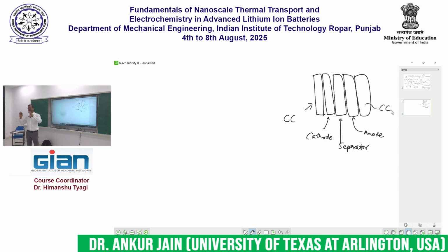So if you think of a cylindrical lithium ion cell that has a jelly roll of this sandwich of 5 materials, then the effective thermal conductivity of this heterogeneous body will be determined by the properties of the individual materials that make it up.